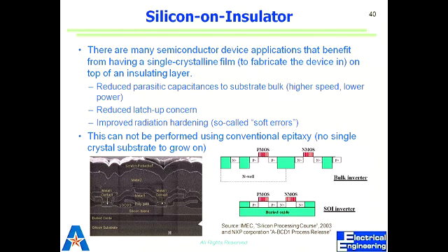And that doubles your real estate. That's exactly what we use. All these new microprocessors have SOI technology. They're made on SOI wafers, so we make it on top of an insulating film. Having this buried oxide gives us many things. It gives us isolation from the other side. It reduces the stray capacitance, latching up between two devices, and improves radiation hardening. So much less defects because of radiation.